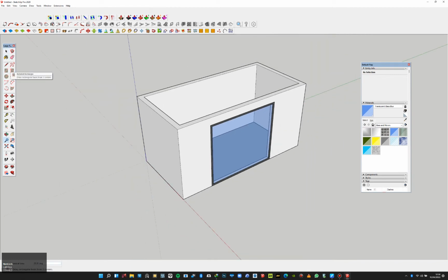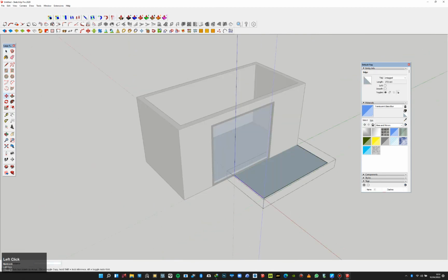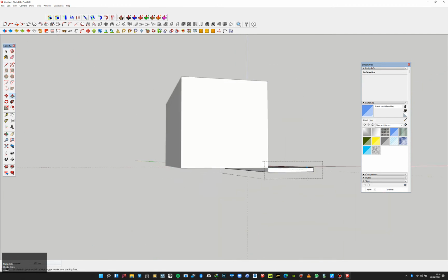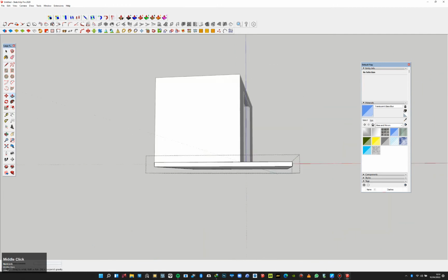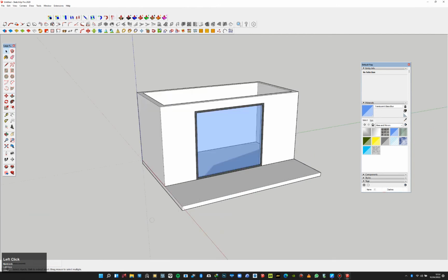color. Then I go to the rectangle tool and I try to draw the veranda. I pull that edge. I notice some mistakes, so I repeat. I draw the veranda. And I push it out by 150 millimeters. Now we have the veranda.